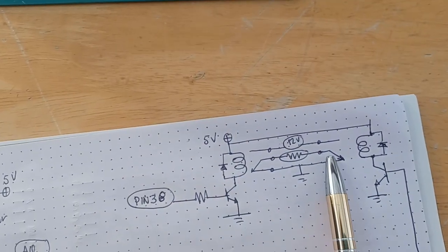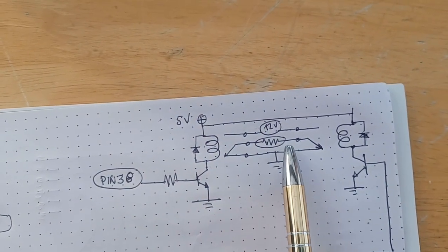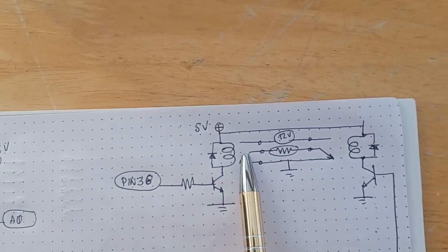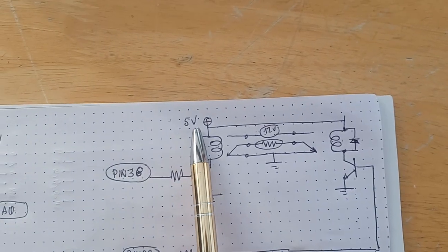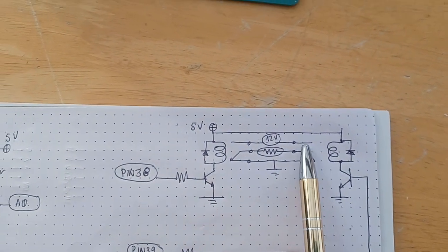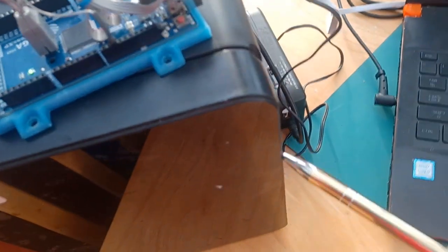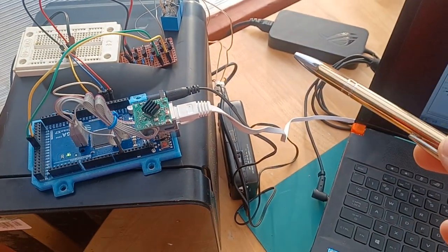couple relays configured as an H bridge, and the Peltier is in the middle, common contacts of both relays, and the relays are there so it can change the polarity. And you know, when you change the polarity on a Peltier cell, you can either move heat from inside to the outside, dissipate it through the heatsink.